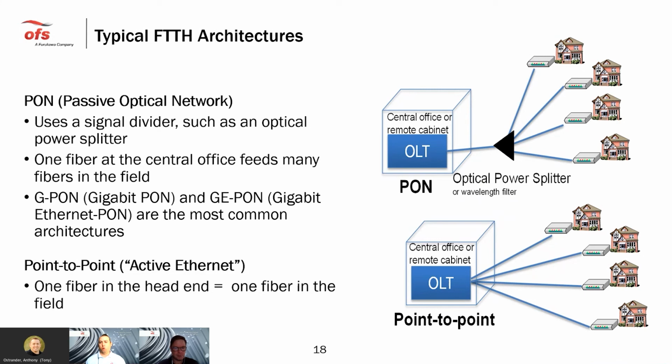With a PON-based network, you're taking a single beam of light from your OLT on a single fiber, and it hits a splitter, and that splitter then splits that light up amongst the customers. In the US, the typical splitter ratio is 1/32. You can do 1/16s, you can do 1/64s, whatever the case, but the typical is a 1/32 split. So you're taking that single beam of light from the OLT and splitting that signal up for each of your customers, or in most cases 32 customers.